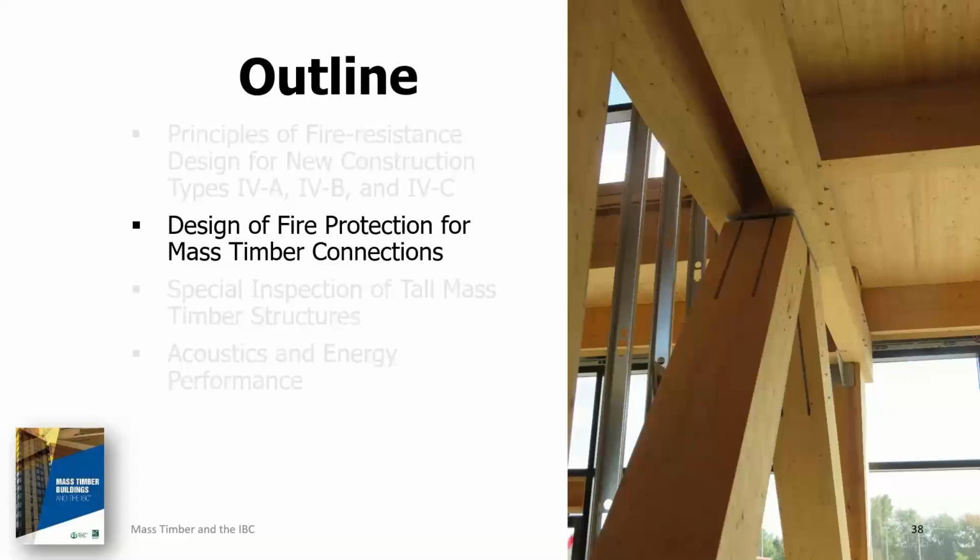So while the connection shown in the photo on this slide would be acceptable in type 4HT, or traditional heavy timber construction, it would not comply with the prescriptive provisions for types 4A, 4B, and 4C construction without additional protection being added over it.